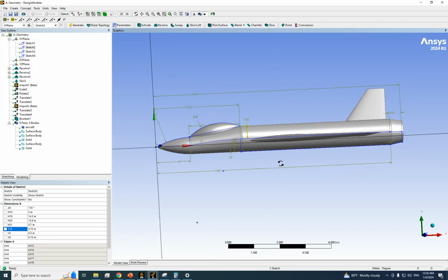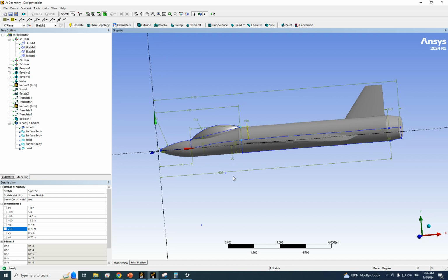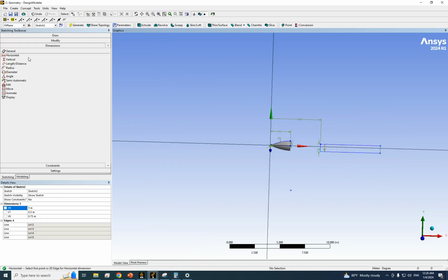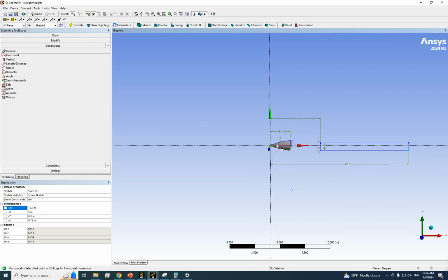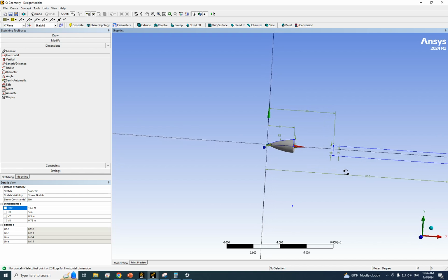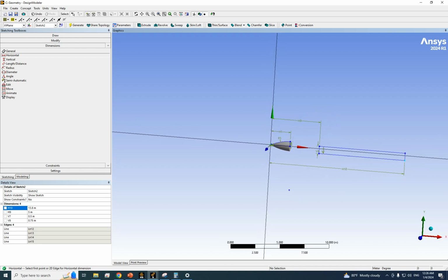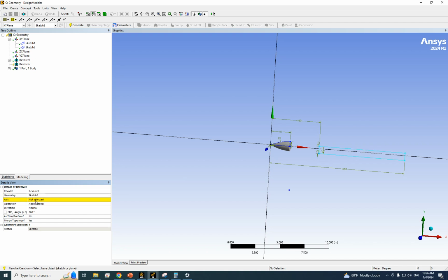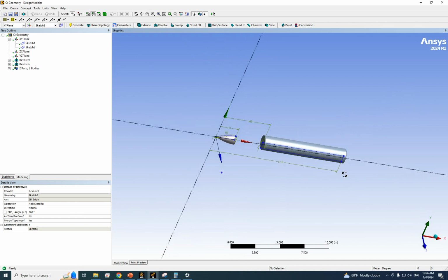the distance between this H20, so this part is 13.8. Let's go back to here. This one to here is 13.8. Yes. Right. And then you go to modeling mode, create, revolve, about this line, apply, generate. Now you have the cylindrical body.